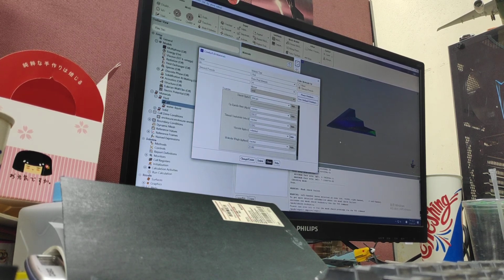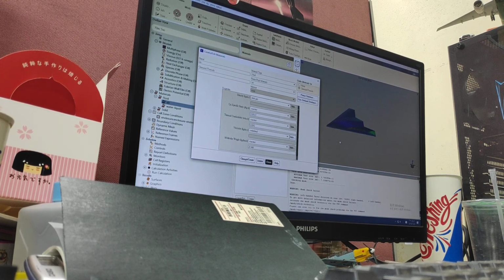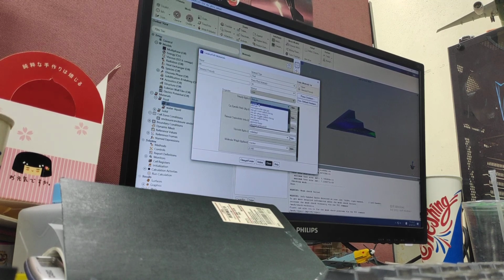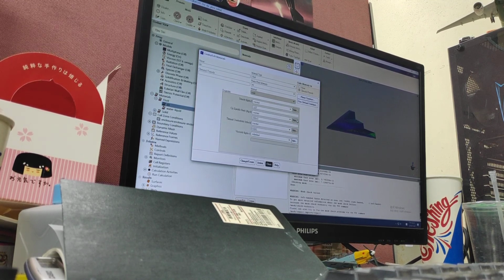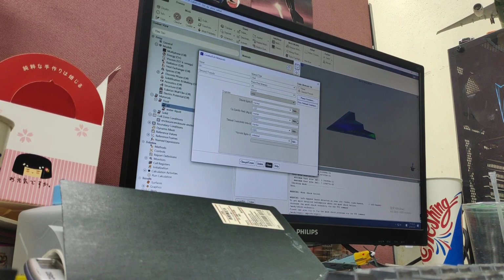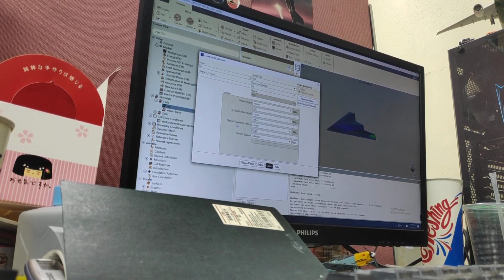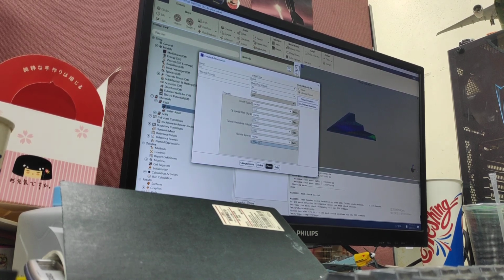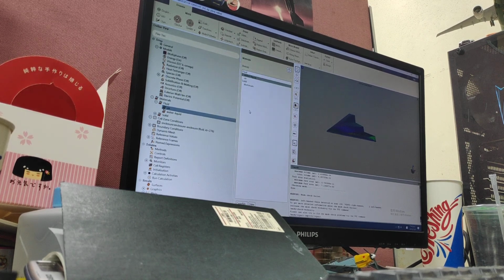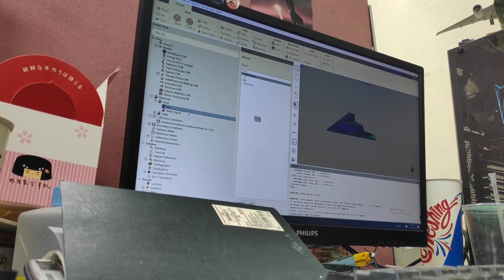For us, we're going to do the flow at low speed, right? If you are doing low speed aerodynamics, just use constant, and for viscosity just use constant. Don't need to use the Sutherland law. But if you want to use water, yes, okay.